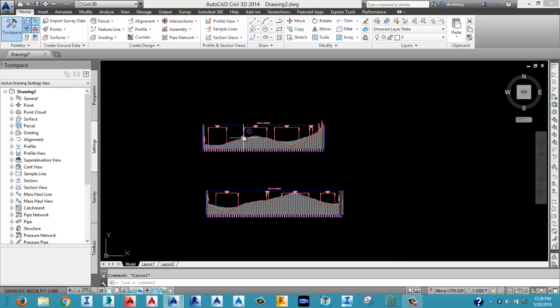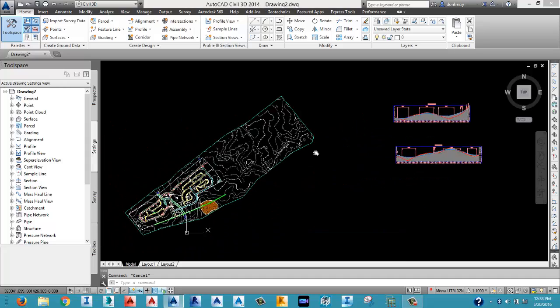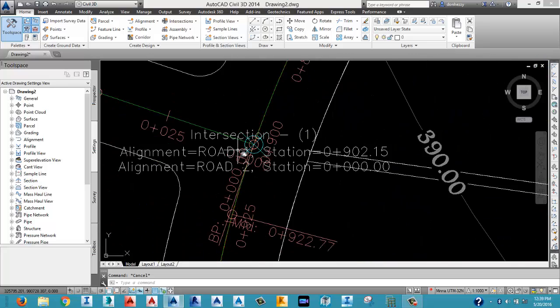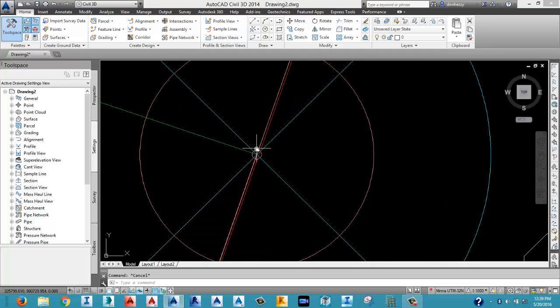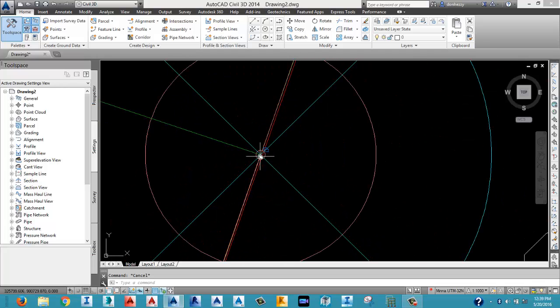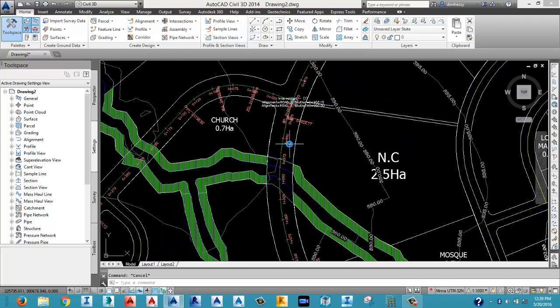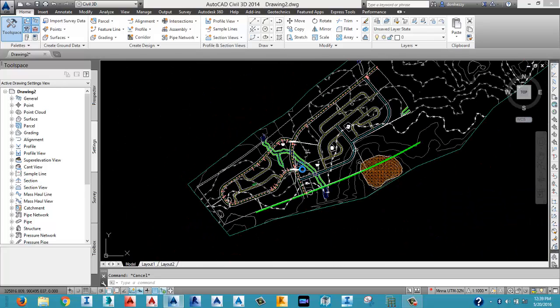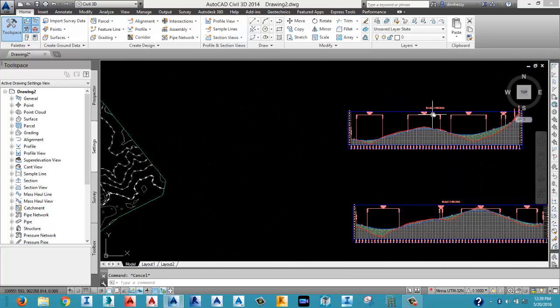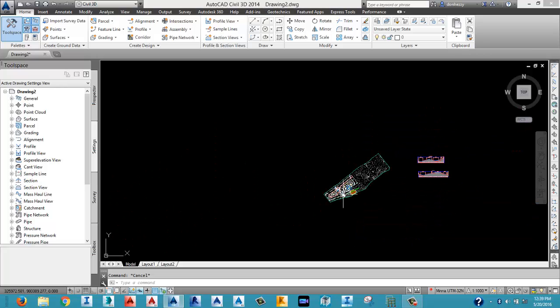So the process of achieving that is, one, you create a block, and inside that block on the point of intersection on your plan view, like we have this is a plan view, the first intersection point, I insert the block here, and I come to my second point here, I insert another block. How do you insert the block? I'm yet to do that. We'll do that now. So first thing is just create a block, insert the block here, then come here again, you create another block. Then you go to your profile where you want to project, you select that profile, then you project the information where you have on your profile 2 on your profile 1. So let's do that now.